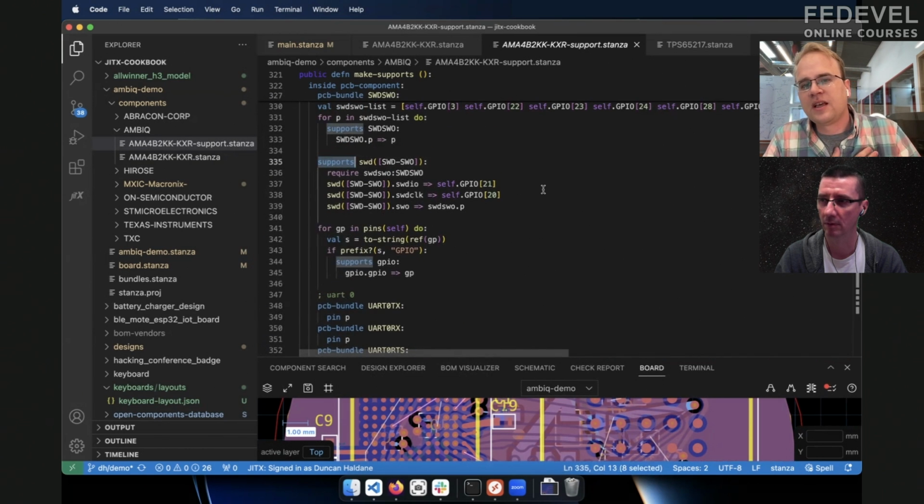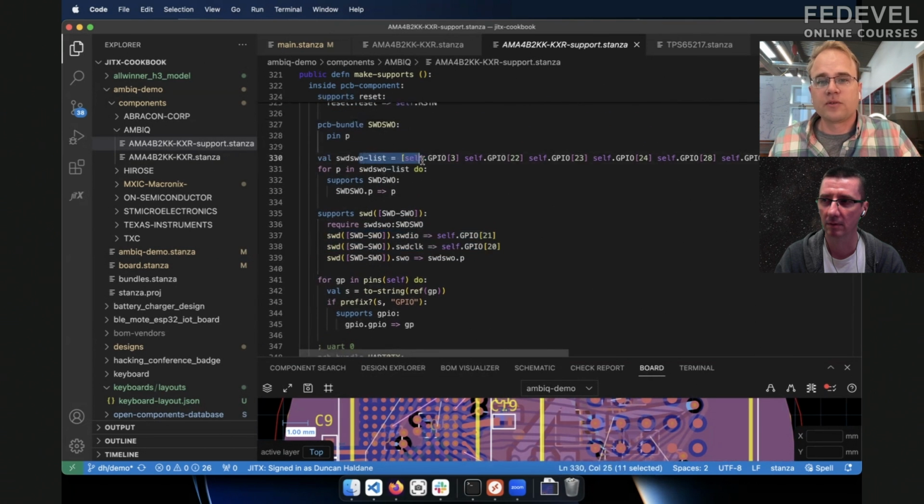So this says, I've got this SWD interface with an optional pin, SWO, which you don't necessarily need, and it's available on these pins. If you end up using this, you'd have a require statement saying attach SWD. There is only one place for this, so it will be on those pins. Other things could also be on those pins, like SWO, for example. Okay, this could be on any one of these pins.